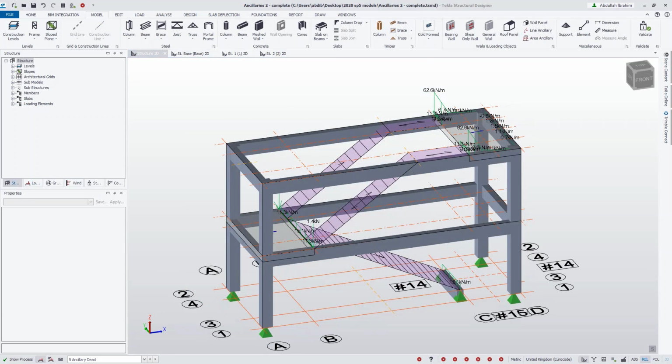So the last thing I'm going to show with regards to ancillary load is decomposition of loads that don't end either at the edge of a slab or on a beam. So far, all of the loads that we've had decomposed have either met the edge of a slab or have been supported by a beam or an analysis element like we have over here. What I'm going to do is model a walkway at the top, similar to what we did in the previous example. However, it's going to end at this intersection over here.